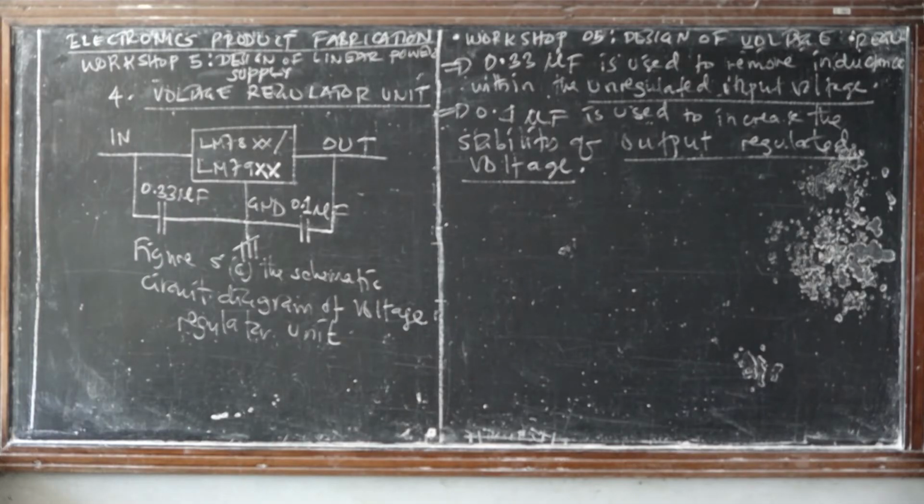It's the manufacturer who gave you the data sheet and then gave you that schematic circuit diagram, that in order to use the voltage regulator that we manufacture, you have to connect it to capacitors as external capacitors. Remember that the voltage regulator consists of bipolar junction transistors, resistors and capacitors, but those should be connected externally.